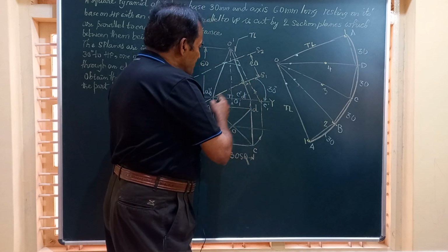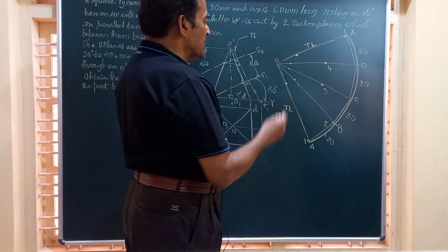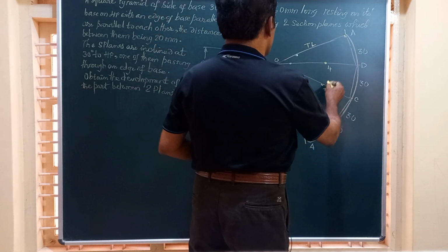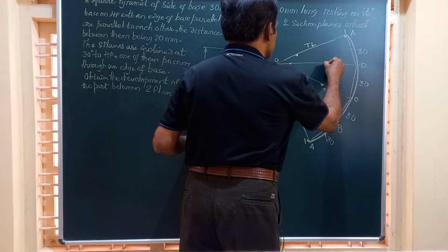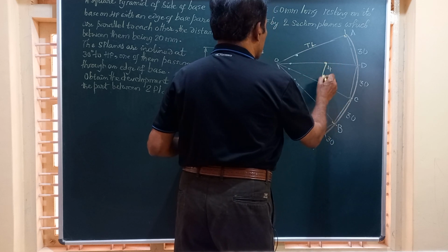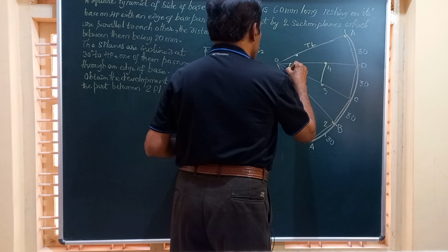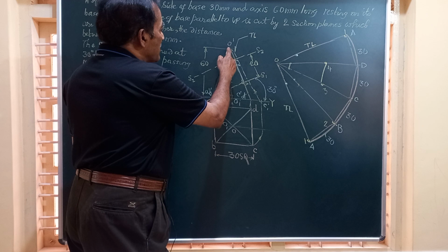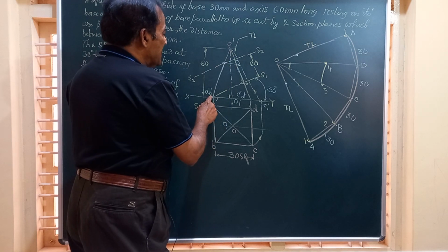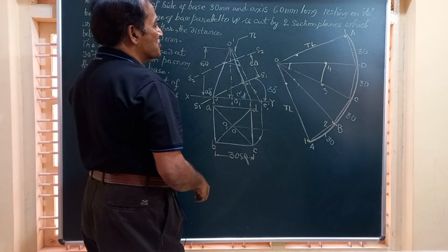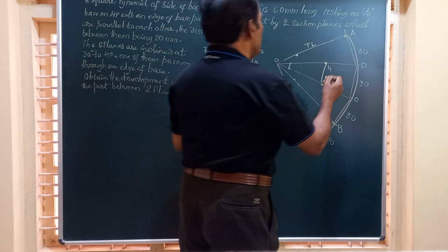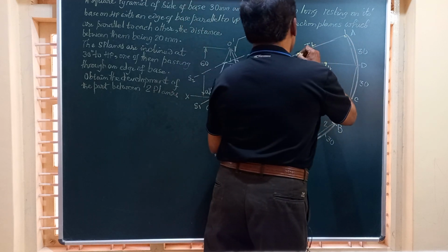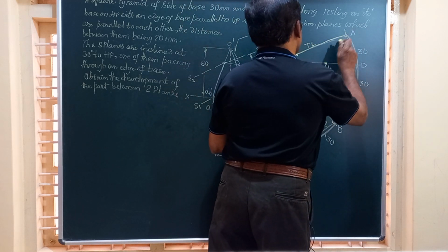So we will take only the first section plane S1, S1 and join all the points so obtained by a straight line. Okay, we can have this joint here. Similarly, another parallel line we have got here, we will join that also. Friends, here you can see on OA and OB, points A and B exist, only the upper portion is removed. On OA and OB, this exists. So I have to show this by a dark line.